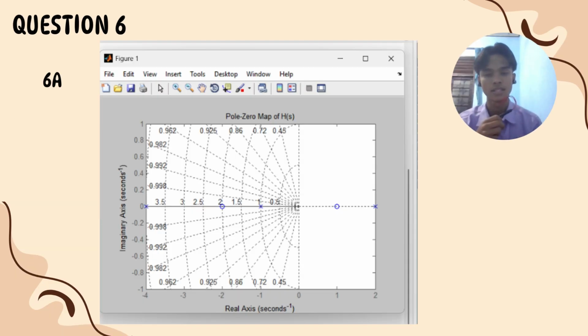Hi, my name is Nazim and I'm going to talk about question 6. In question 6, I analyzed a system using Laplace transform. I used MATLAB's residue to find the impulse response, which is h(t) equals 1.6667 e to the power of negative 4t plus 0.6667 e to the power of 2t plus 0.6667 e to the power of negative t, and t is bigger than 0.